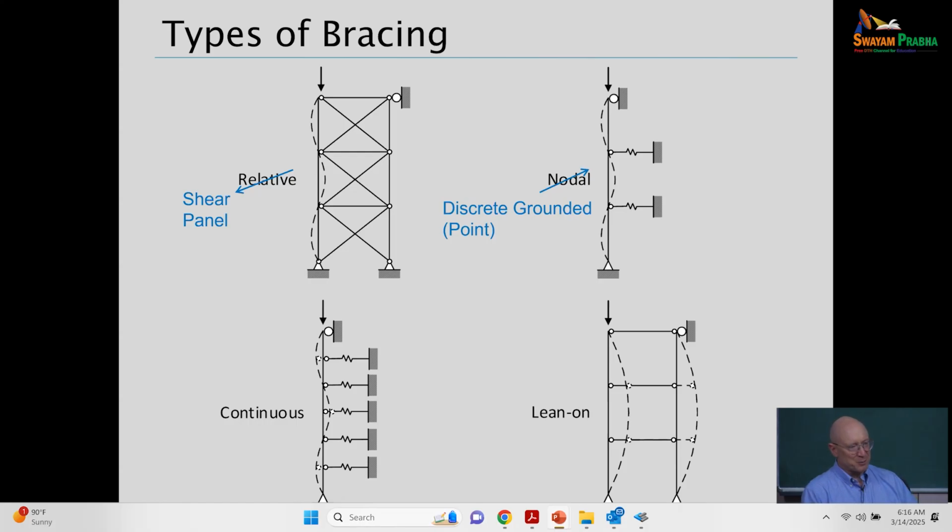The railroad ties are providing essentially lateral bracing in the vertical direction to the rail. And what happens on a very hot day? You get a buckling of the rail, right? So you essentially had continuous lateral bracing, and if it's buckling between the ties, then the bracing worked. If the ties failed, then okay, the bracing wasn't sufficient.